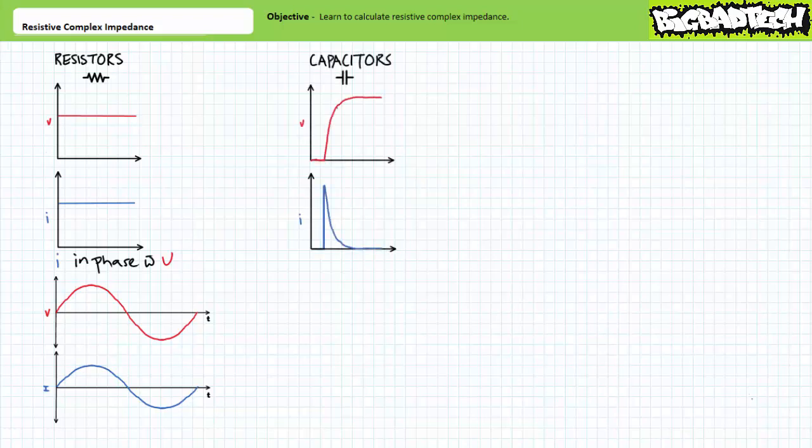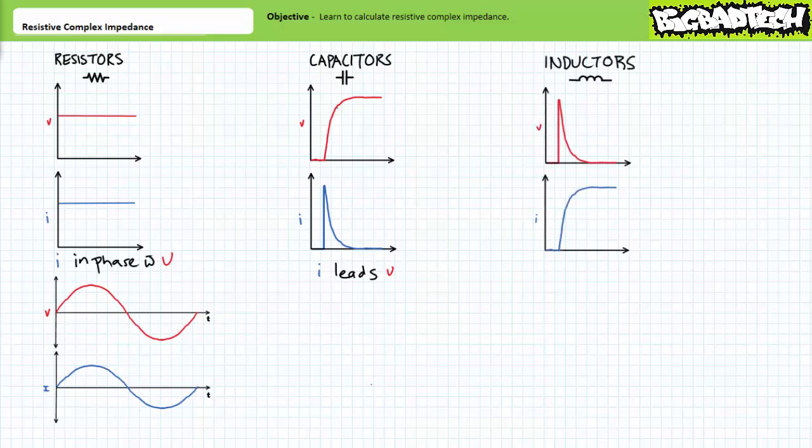Recall from our discussions about the time-variant DC response of capacitors that initially uncharged capacitors experience a current spike followed by rising voltage. This behavior can be summarized as current leading voltage for capacitive elements, and that the current spike occurs before rising voltage. The time constant established by the capacitive circuit under inspection determines how slow or fast this exchange of energy occurs.